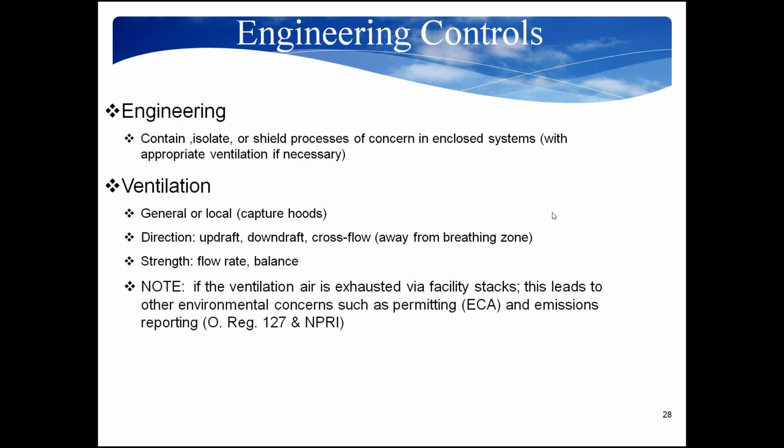You might also have to install some engineering controls. These controls contain, isolate, or shield processes of concern in enclosed systems, and with appropriate ventilation if necessary. The ventilation might include general dilution ventilation or local exhaust ventilation, where you have a capture hood near the process.